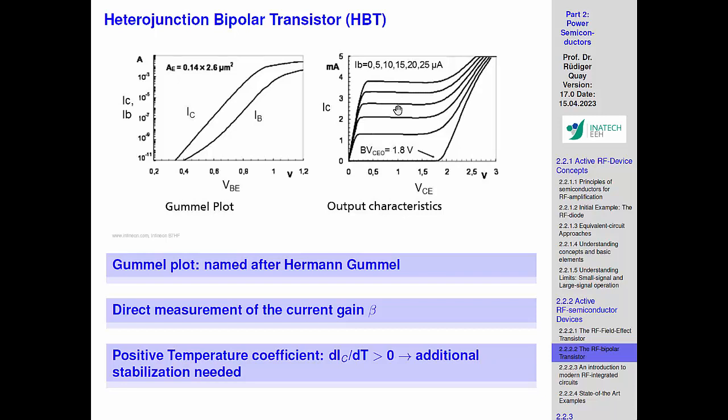And that's a bit ugly because when you produce current, what will happen? More current will produce more heat. And if more heat produces then again more current, which is the meaning of this positive temperature coefficient, that's dangerous because you get in a positive accelerated loop of current generation, and that's what's happening here.